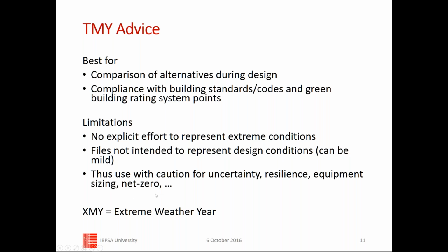So you have to be careful using TMYs for anything that involves uncertainty or resilience studies, for instance, how is the building going to work under a really bad year? Equipment sizing is often dicey with TMYs. Net zero analysis, again, what's going to happen in extreme years of one sort or another. You can't just blindly use TMYs.